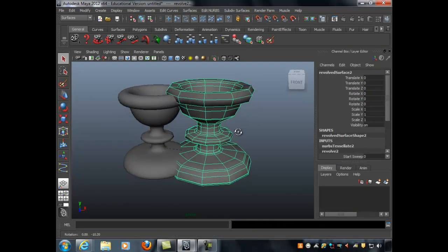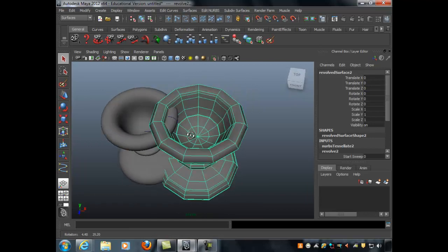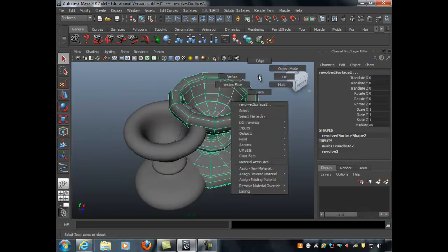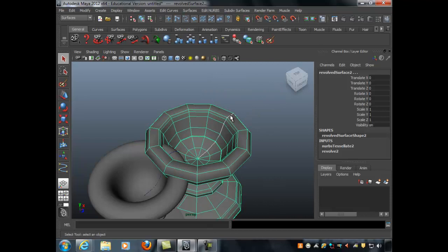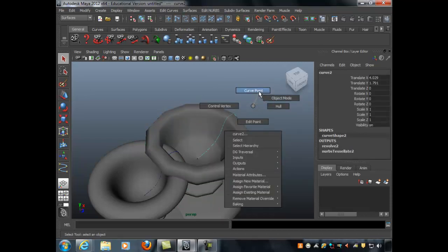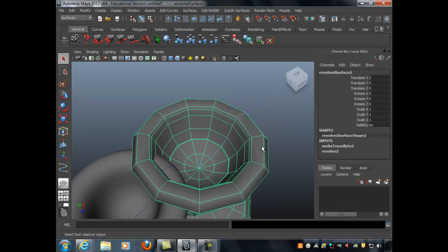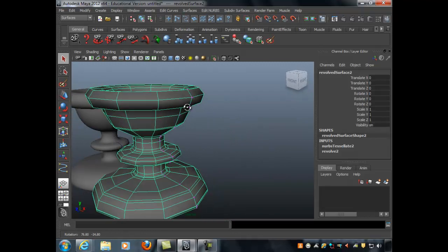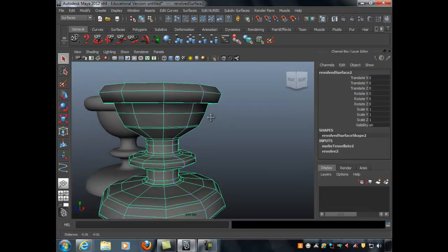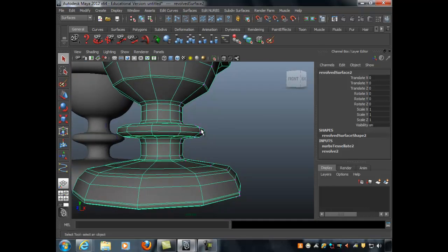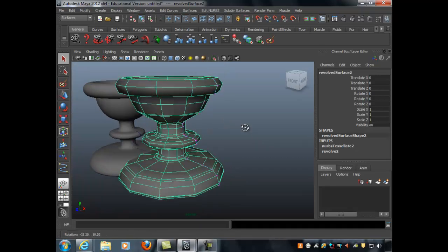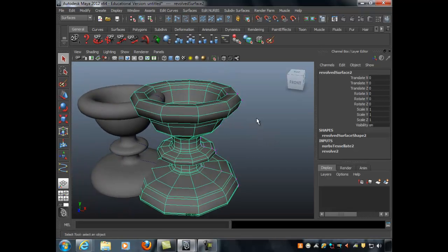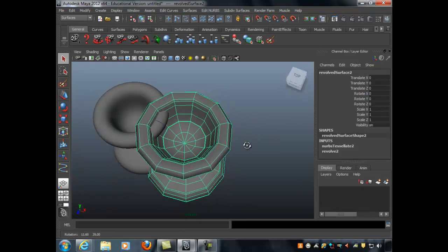And by doing control points as my method, what has happened here, if I select the curve and then select control vertex, you can see that wherever there's a control vertex, there's also just one edge, which is nice. Because doing it this way, using control points, has allowed me to basically do an optimized mesh. I've made this mesh with only the minimum number of edges that I need to define that shape, and I've made the mesh so that this is my control cage object.